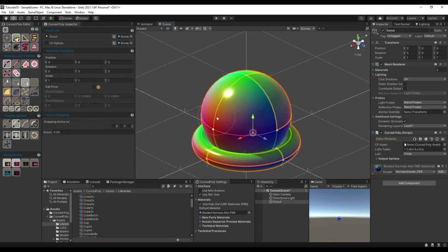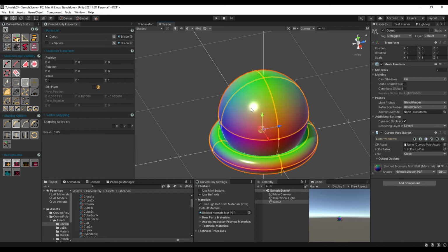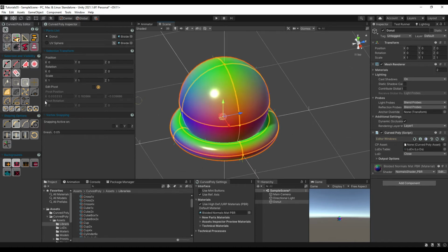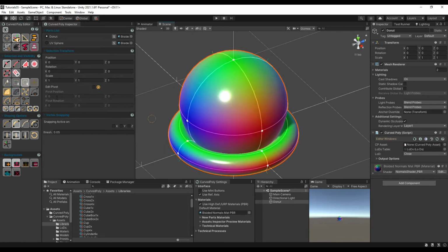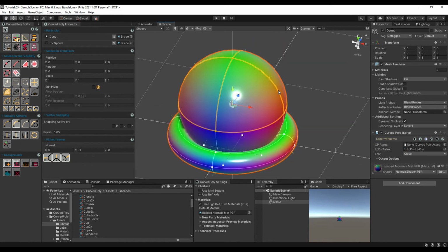For all the selection tools we have the option to activate the cumulative variant. When cumulative mode is disabled, any picking or selecting action will clean the selection. When cumulative variant is enabled, elements can be selected in more steps, since the selection is never cleaned. So, for instance, in Vertices mode, with the Pick tool and cumulative variant, we can select, one by one, all the vertices of a polygon to get it selected. There are also a few actions to know about selection. You can select everything or remove everything from the selection, with Select All or Unselect All.